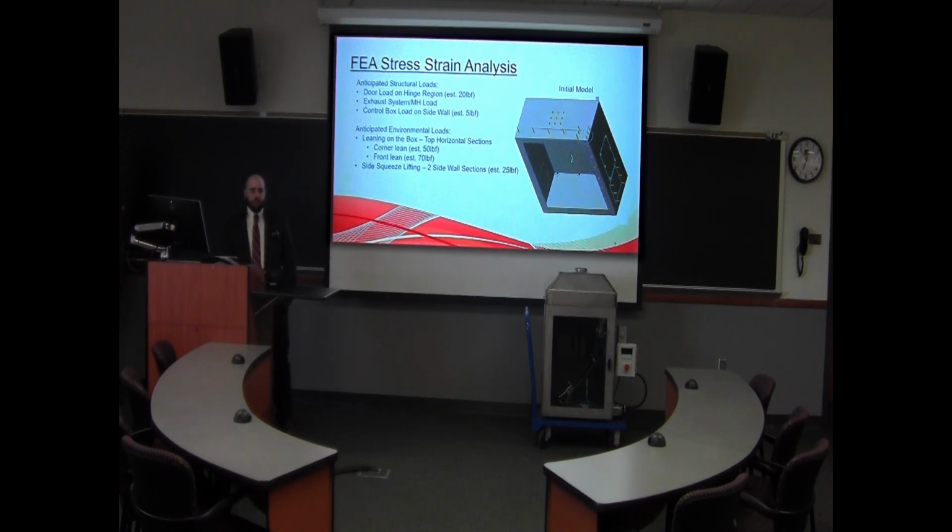So we developed an initial model early on in our design process to get a rough idea of what the most significant loads on our cabinet would be when it comes to resultant stresses. The structural loads and environmental loads are loads that we anticipate would be the most significant in our cabinet. The structural loads are loads that are static, resulting from components of the cabinet itself. The material holder fixtures on the inside and the weights that they present, the electrical box on the side, everything that adds weight to our cabinet.